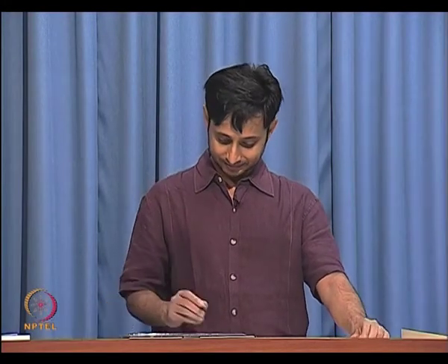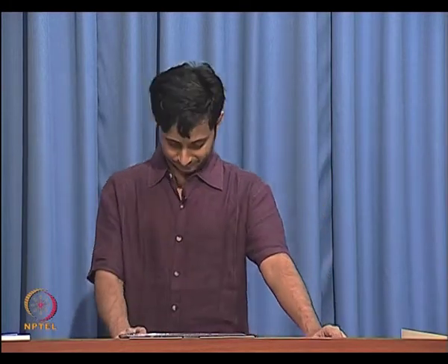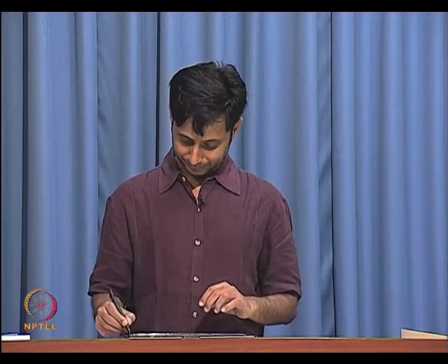When the distance between the two plates is comparable to the length and width of the capacitance. That is when the fringe capacitance becomes very important. If the distance is much smaller than the length and width, then the fringe is really a little bit extra, right. Otherwise, when the length and width are comparable to the distance between the two plates, then the fringe capacitance is going to be huge. All right.